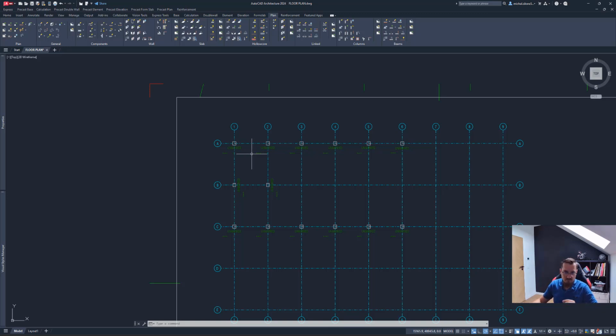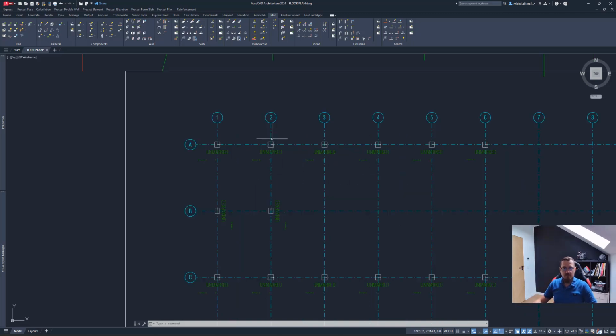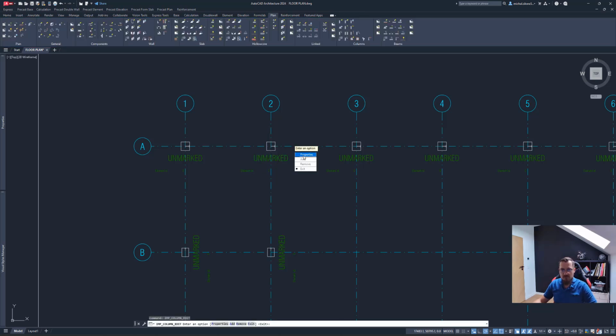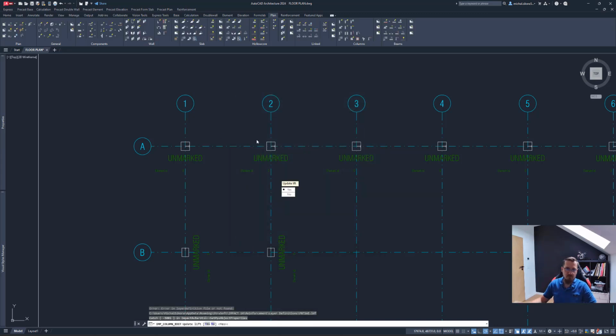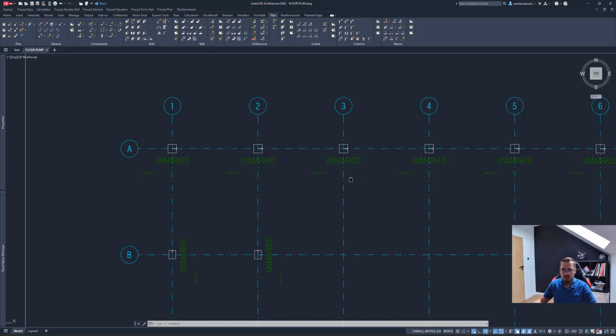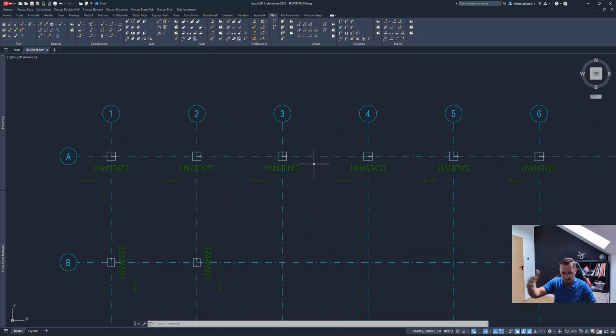What we can do now is play around with the reinforcement of those columns. So let's go back and open up one of the columns and go back to the properties, just to remind ourselves. There's a reinforcement, there's a template. This template gives us some insight into how the reinforcement will look. We won't be able to see 3-dimensionally how that reinforcement will look, as this is something that we in Impact for AutoCAD do at the drawing level. So we can apply a template, but the reinforcement we will see only on the drawing. So not a problem there.